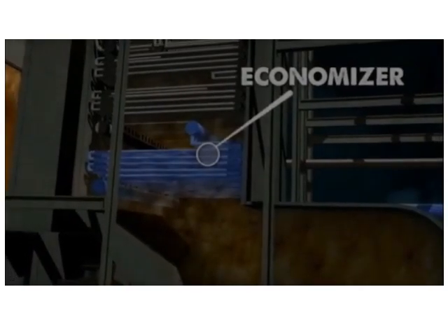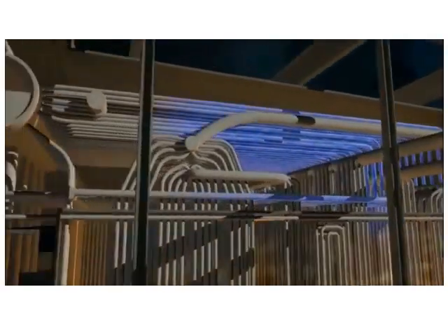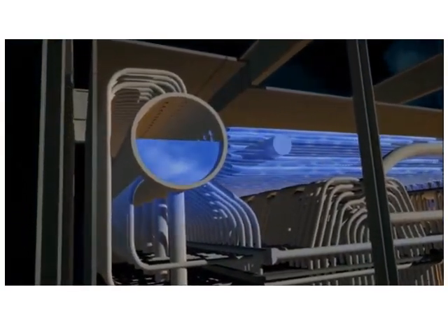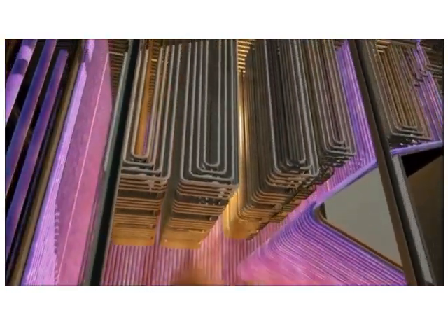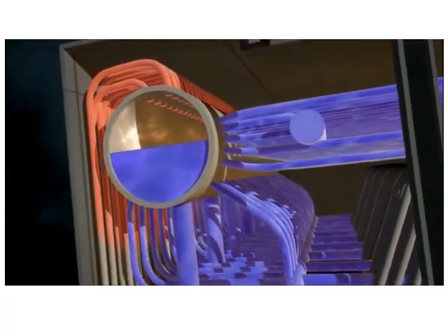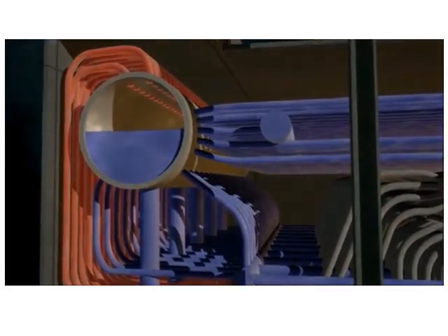And in our case, it is a pulverized coal-fired boiler. It requires a more sophisticated combustion control, having several pulverizers. Each pulverizer supplies a group of burners that are located in an open or compartmented windbox. Primary and secondary air are admitted and controlled on a per pulverizer basis. Let us leave the details of this control strategy for our discussion later.